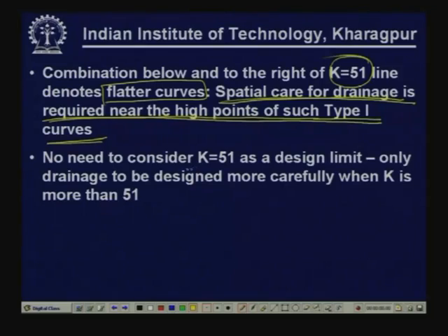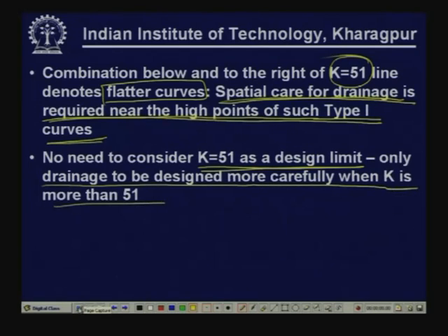Certainly, it may be acceptable, but we have to keep in mind that if k is more than 51, then special care or attention is required for drainage purpose. That is all. So, no need to consider k equal to 51 as a design limit. It only says that drainage is to be designed more carefully when k is more than 51.